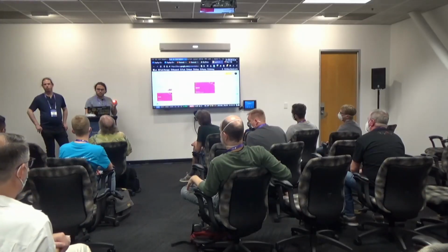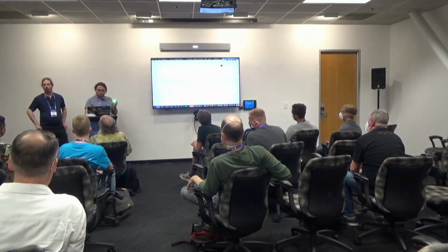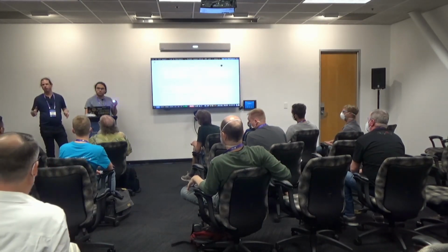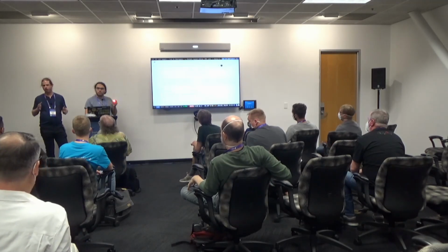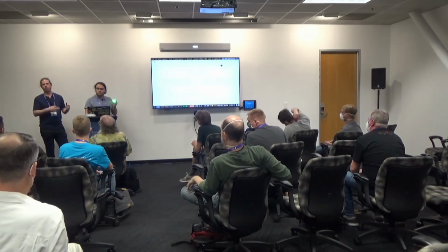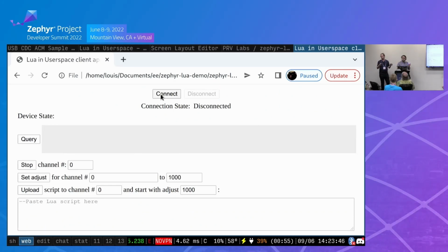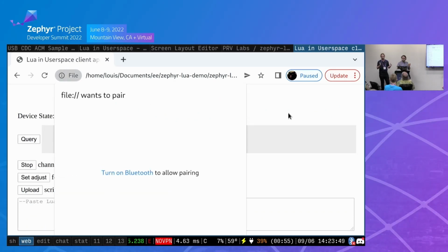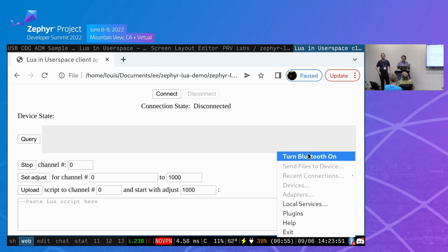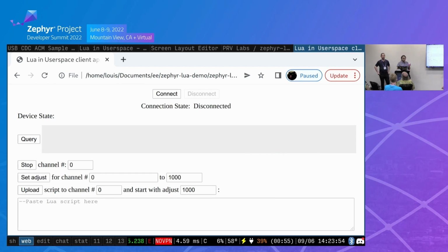We didn't have that issue, probably in large part because we decided to put all of Userspace as just one contiguous region. If you want to do more partitions, I think you are going to run into that because the kernel has at least 2 bounds, probably more like 4 or something, depending on where everything is laid out. Userspace is well designed in that it will reconfigure the MPU with every context change. So you don't need to have as many MPU slots as you do total partitions. You just need as many as you have exposed at a single time.